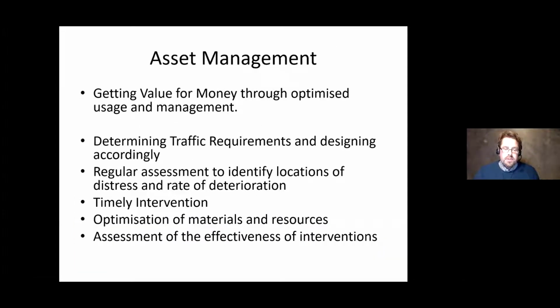In terms of asset management, it's a fairly simple concept. It's about getting the value for money out of your asset through effective usage and management. In terms of pavement, it's about designing for what you're going to use, what you're going to need. Essentially, it's about knowing what your traffic requirements are going to be. It's about carrying out the proper studies, knowing what demand is going to be there and how you're going to effectively use that over what sort of time frame. It's about choosing materials that are going to be effective for the environment they're working in and for the usage, and these days we need to be conscious about the recyclability of them as we move towards circular economies.